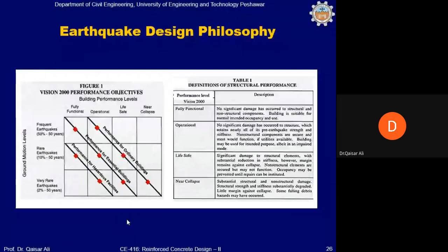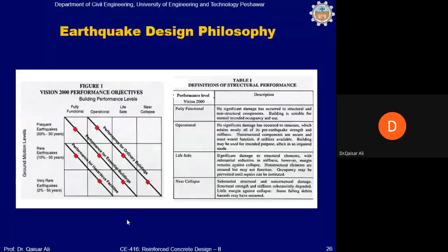If the building is allowed to get damaged due to these rare earthquakes, and if the damage is recoverable or repairable, then I think it will be an economical approach, because designing a structure so that it is always undamaged when hit by any earthquake will be too uneconomical, and the initial investment will be too high. It will almost be not affordable even for very rich people.